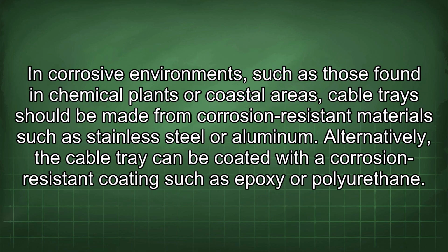In corrosive environments, such as those found in chemical plants or coastal areas, cable trays should be made from corrosion-resistant materials such as stainless steel or aluminum. Alternatively, the cable tray can be coated with a corrosion-resistant coating such as epoxy or polyurethane.